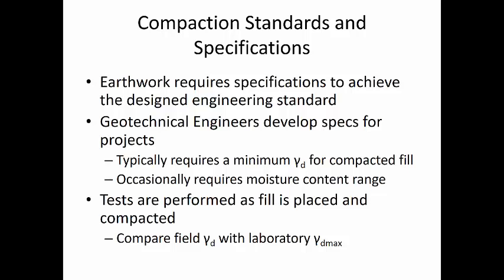And oftentimes, for large projects with various types of fill being placed, you will have specifications that are changing, rearranging, and moving depending on what the application is. Sometimes you'll get a road or parking lot subgrade and backfill of a foundation of a structure, and maybe backfill of trenching of pipelines, and maybe all three of those would have a different type of compaction specification for that project.